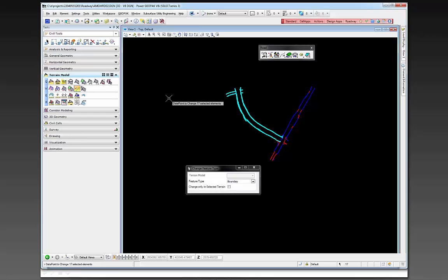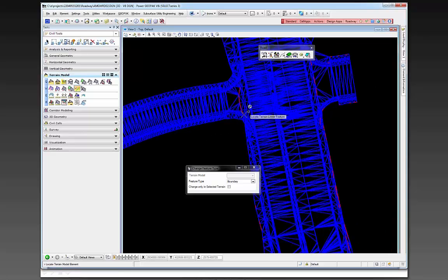So automatically it finds the number of elements here, and then all I have to do is basically it knows that they're part of that DTM proposed surface, and I just basically change those from break lines to boundary lines. And it's just a matter of doing that, and then the surface retriangulates, and you'll see now that it's actually forming the triangles inside of my cut fill boundaries. So it's like a two-step process. You select all the lines first, create the DTM with a maximum triangle length, and it can be 1,000 for it doesn't really matter, as long as it forms the triangles across the break lines, whatever the break line distance is.